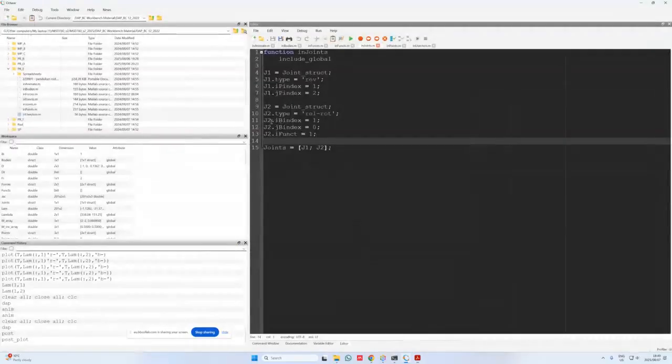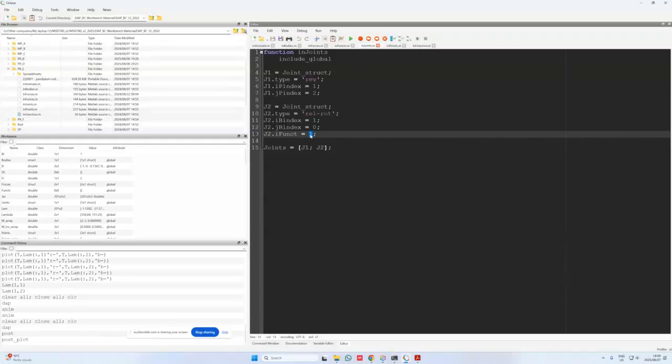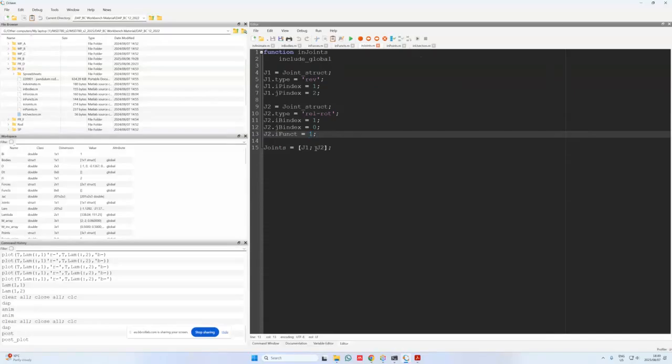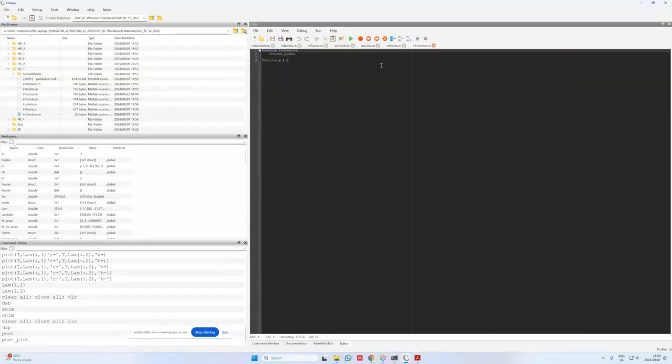Right, so how do I do it over here? IB index is going to be body 1, so the pendulum rod. The relative rotation driver acts between the pendulum rod and ground, so IB index is 1, JB index is 0, and then the index of the function is 1. If I go back in funct, it's going to be index 1, which corresponds to f1 over here. Okay, so that I then specify as a joint structure, and I simply add this to my joints list. Other than that, in points and in u vectors essentially remain the same as well.